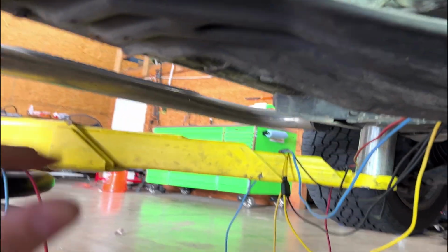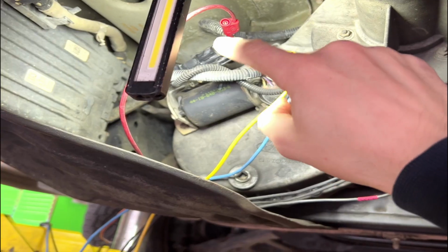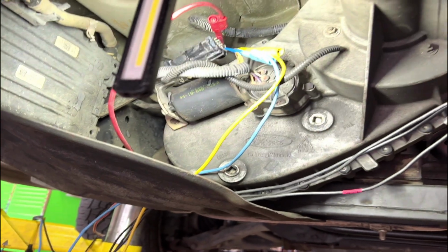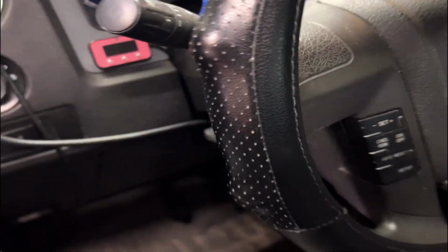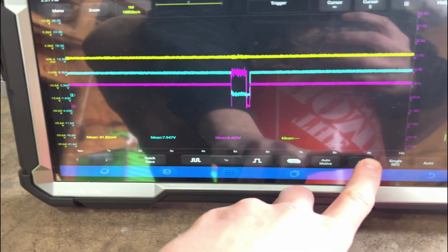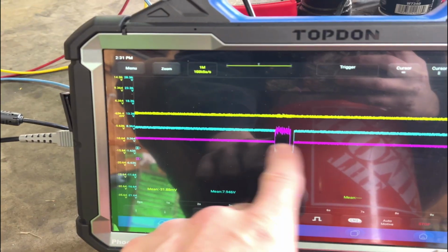So now I'm going to spin that scope around. We'll go up, hit the knob and see what changes down here. I don't want to pull that connector out yet, just in case our connection issue is in that connector. We're going to make sure we catch it correctly. Scope is rolling. We'll step on up and hit our 4 high. Heard something click. We got a couple changes. We will come and hit run, which is actually stop. Oh, that's interesting.